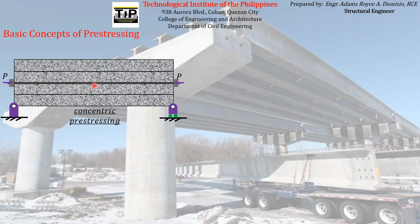So the type of pre-stressing in that scenario wherein the pre-stressing reinforcement is located at the centroid of the cross-section is what we call concentric pre-stressing. So why is it called concentric pre-stressing? Obviously, because the pre-stress force P acts concentrically, or along the centroid of the cross-section. That's why it's called concentric pre-stressing.